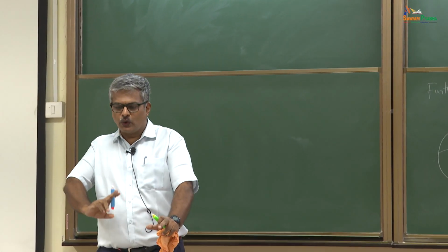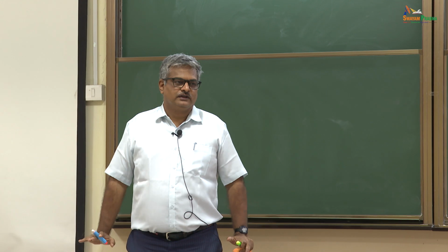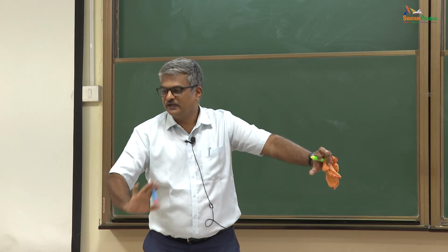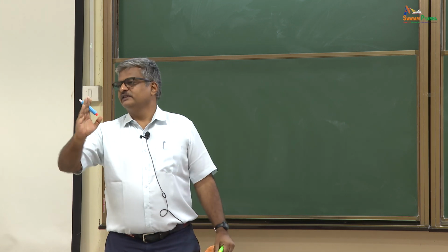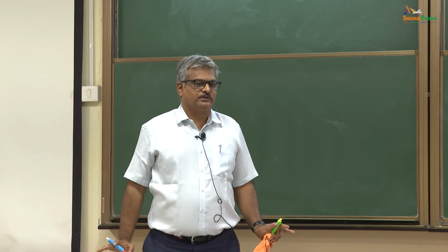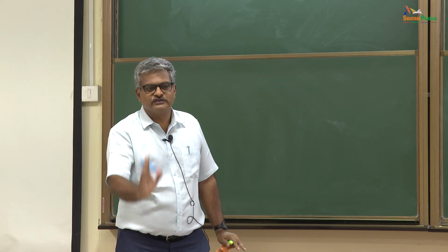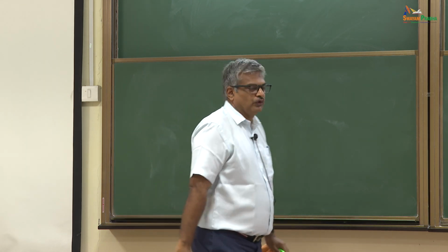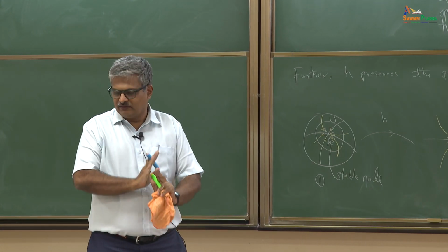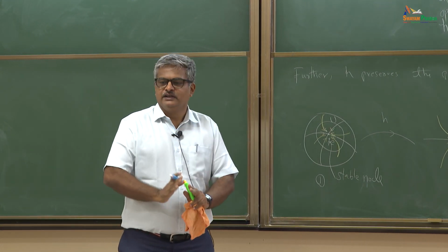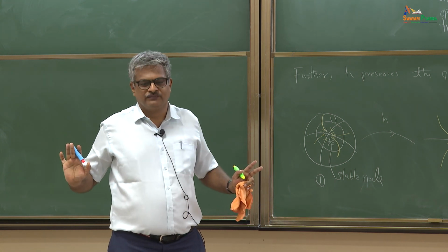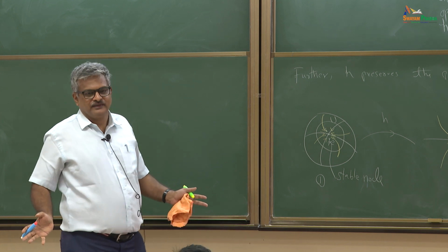If you end up with even one zero eigenvalue, that's it. You cannot comment anything about the nonlinear system based on linearization. If it is strictly on this side or that side of the j omega axis, yes, you can comment, but not when it is on the j omega axis. So we don't use words like marginal stability. We want to be very clear: you either comment, or when you are on the j omega axis, we say we cannot comment. We don't have any terminology for that.